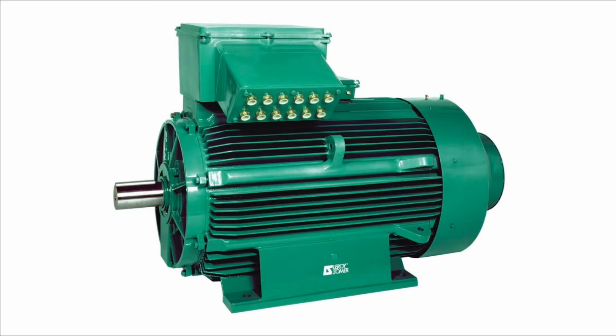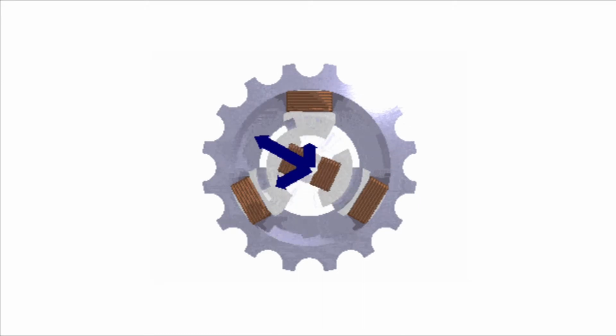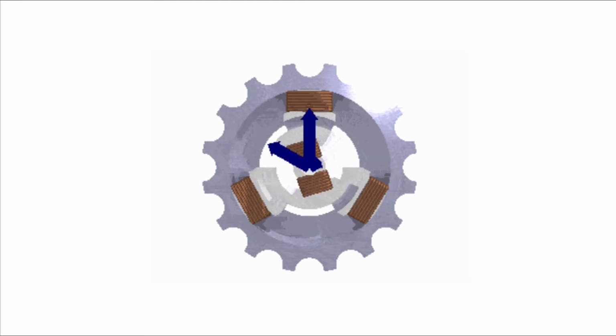Each one has two main parts, the rotor in the center that spins and the stator, which is on the outside and is stationary. For a synchronous motor, the rotor is the part that turns the shaft. It is usually lined with permanent magnets that get attracted to or repelled by the stator. The stator is a non-moving shell, and it has electromagnets that move the rotor. AC current is put through the coils, which in turn makes them act as bar magnets to attract and repel the motor. The phase is shifted so that the magnetic field will turn in a circle, which then attracts the rotor.